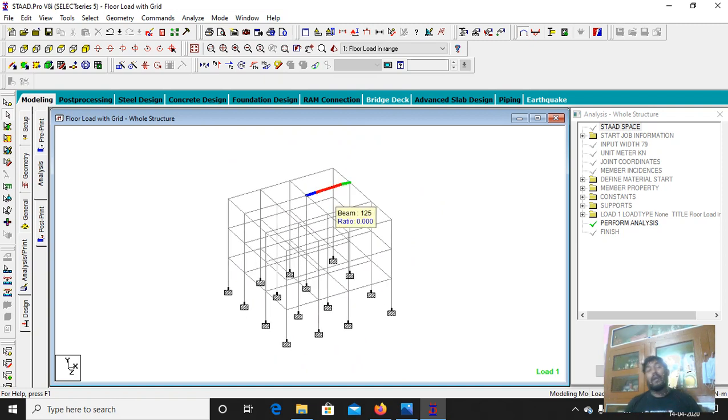So that's how a floor grid with any part can be left out in a building. There can be more than one part, there can be more than two parts. Any parts can be left out in the building by defining the ranges. So this is the usefulness of range. In building design, there will be a staircase, a lift lobby, etc. Sometimes there is no floor in a grid. For those cases, we need that concept of the zone. This is a very important part.